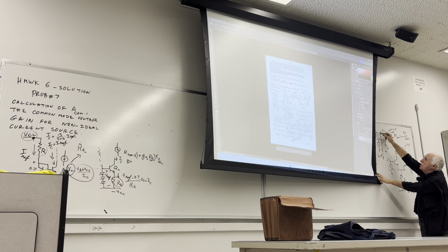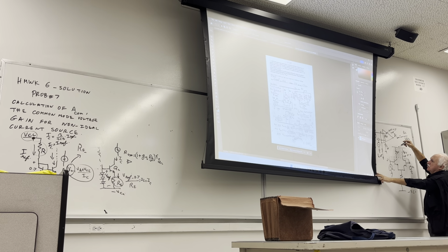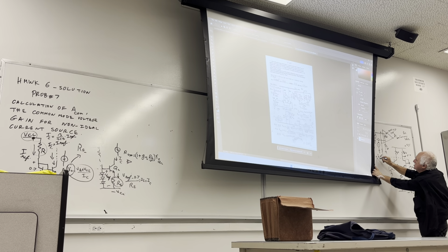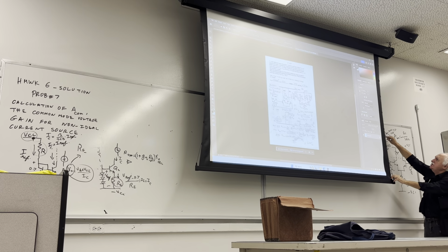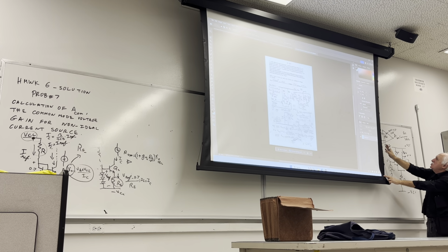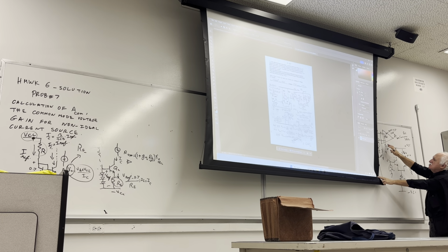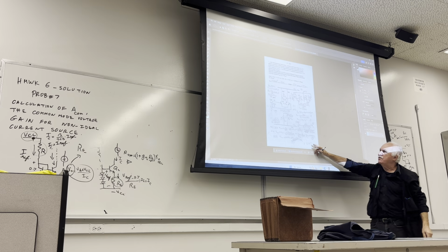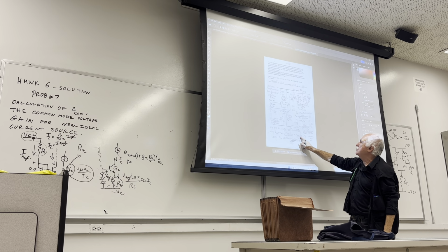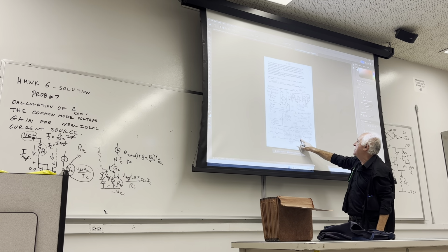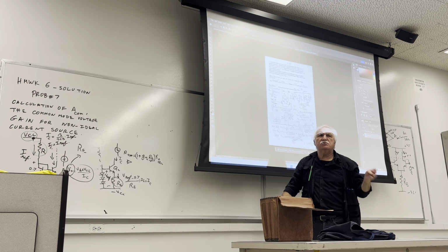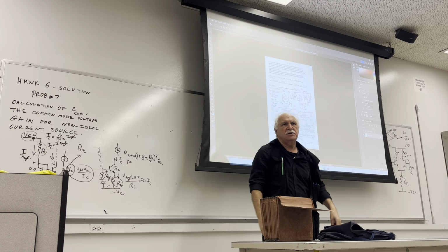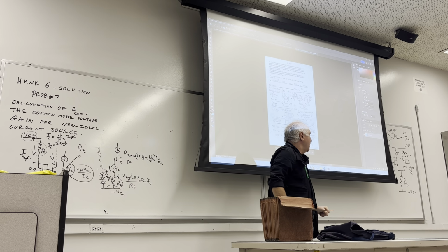And that is when you apply a common mode input. Actually, this is twice RCOM, times 2. Because when you join them, when you short circuit them together, you look at the input, you see 2 RCOM parallel to 2 RCOM, which is equal to RCOM, what we calculated over here. R common mode. Input common mode resistance. And it's a very large resistance. Usually we ignore that resistance in the calculation.